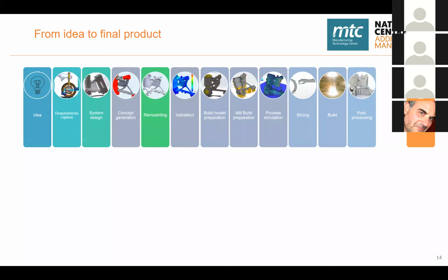And okay, we do the post-processing, we remove the supports, we do all of that, and then I get the final part. In reality, when we do a functional product, we need to know if what we get out of the manufacturing is the right output. So what we need is to inspect our parts, measure them, or even in some cases, depending on the criticality of the components, scan the parts and look inside of the components to see if the part is properly produced.